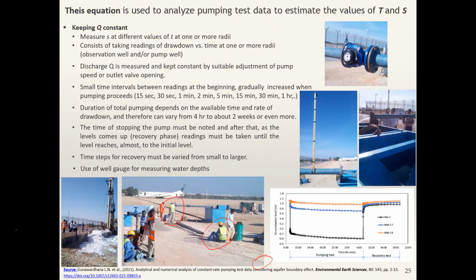I have seen in Canada, there was a case where the pumping test was continued for 1 whole week. All right. So then only you can assume that the flow reaches the steady state. Okay. So take the drawdown with the time. That is the pumping test.